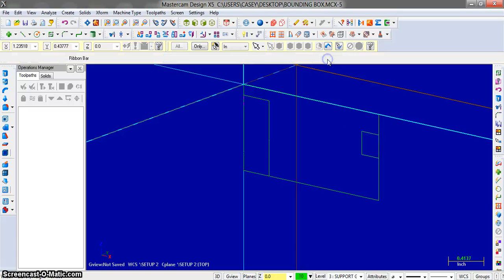So there it is. And make sure to fillet this after doing it beforehand, and make sure that the radius is 0.063. There's your radius, there's your fillet. Click OK. Now you're going to do a trim. Make sure that you have divide and delete selected, and just make sure to double click everything because you made 2 rectangles. So there's your divides and deletes.